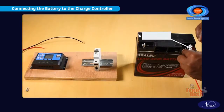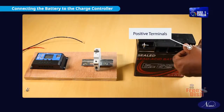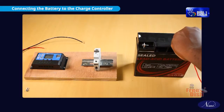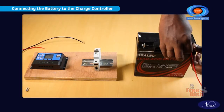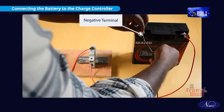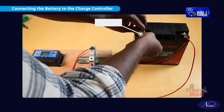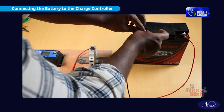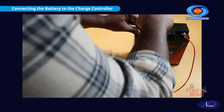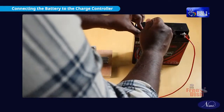Connect the lug terminal of the red wire to the positive terminal of the battery, and the other end of the wire to the positive battery terminal of the charge controller through the DC circuit breaker. Connect the lug terminal of the black wire to the negative terminal of the battery, and to the negative battery terminal of the charge controller. Keep enough tightness using the screwdriver.